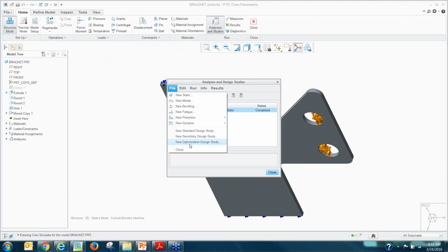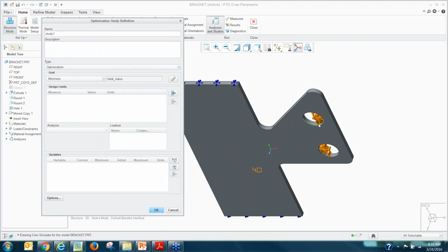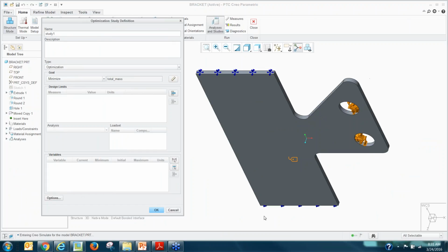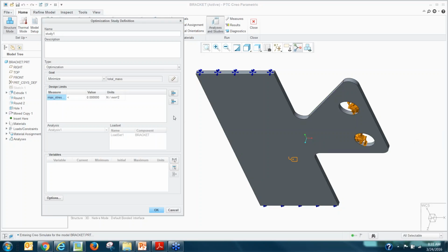Now what I could do is say I want to do an optimization study, wherein, in a mass production scenario, I'm worried about material costs and I don't want to over-design. During my industry days, I've done that. I'm guilty of that too. We all over-design. But it could be reducing the thickness, or just saving on material costs. I could say minimize the mass and make sure the maximum von Mises stress is less than, let's say, so many megapascals.